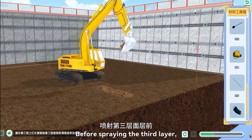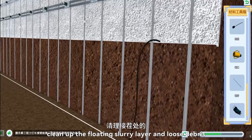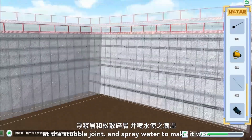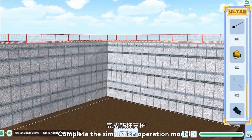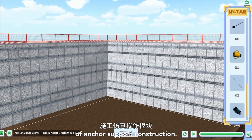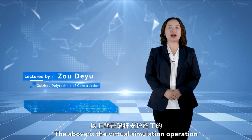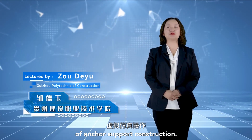Before spraying the third layer, clean up the floating slurry layer and the loose debris. Add the stubble joint and spray water to make it wet. Complete the simulation operation module of anchor support construction. The above is the virtual simulation operation of anchor support construction.